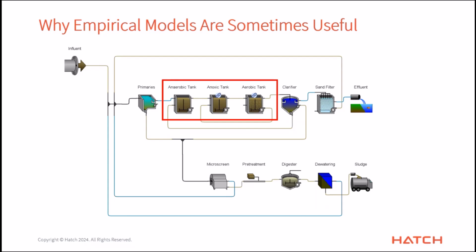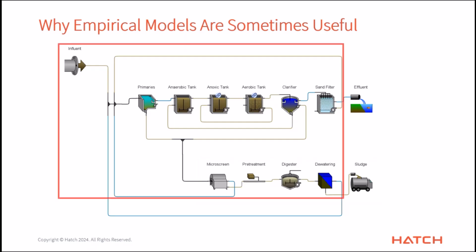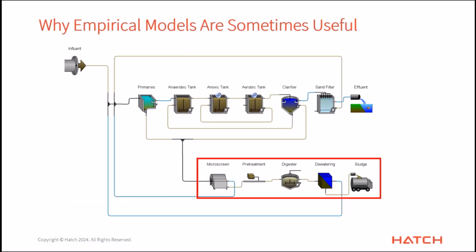So that's often how I advise people to make a decision about which model you want to use. If I'm really just focusing on the biology of what's going on, and I'm okay with the idea, or studying just what's happened in the biosolids handling section, and I don't really need to have a predictive clarifier model, then I'd say go for it. Just use the empirical model, set it so that it's removing 95% of the solids, and you're on your way.